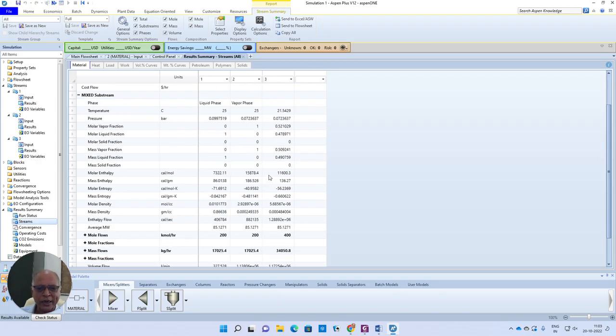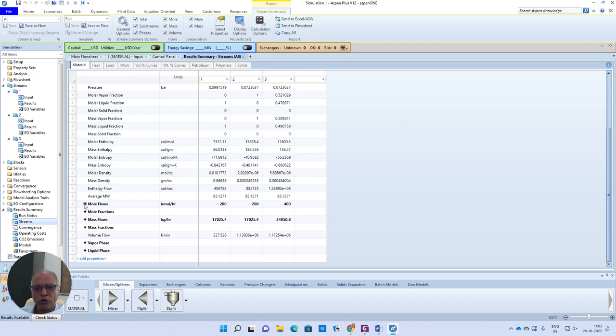By performing mass and energy balances, we will be able to establish, for example, 200 moles each of stream 1 and stream 2 are entering. There is no chemical reaction, so the total moles leaving the process is 400. Now these are component balances: benzene 100 through stream 1, 100 through stream 2. So together they should exit 200. Of course these are given, but we will be able to calculate the composition of the exit stream.